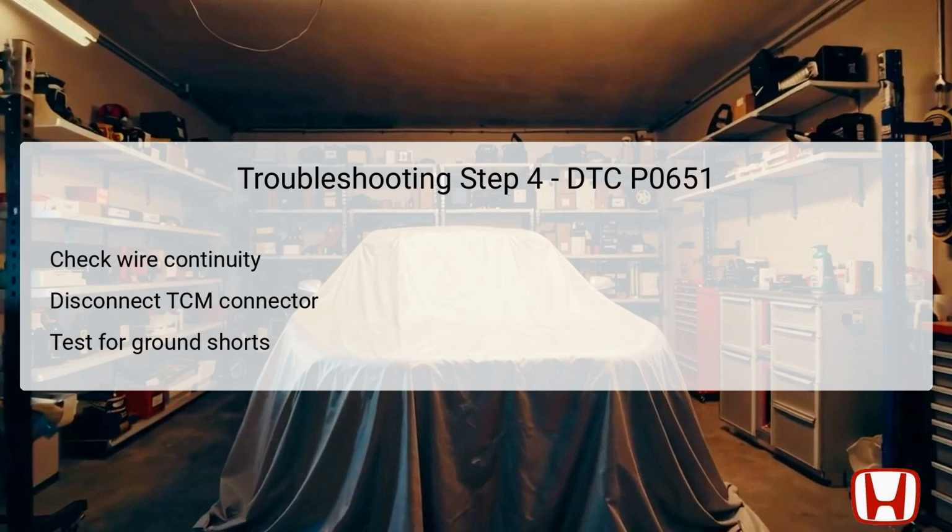In this fourth step, the focus shifts to checking for any shorted wires in the VCC lines that may lead to ground issues. Begin by turning the vehicle to the off-lock mode and disconnecting the 50P connector from the TCM. It's essential to test for continuity between the specified points and body ground individually, while ensuring the vehicle remains off.